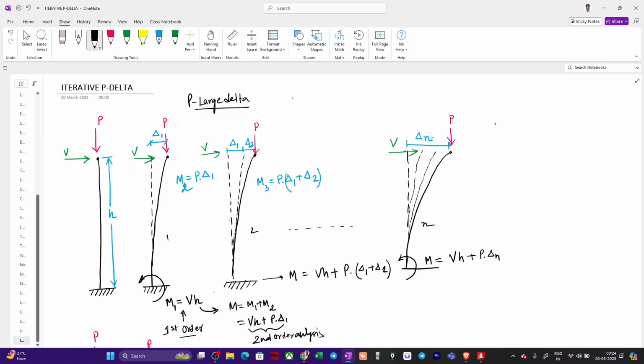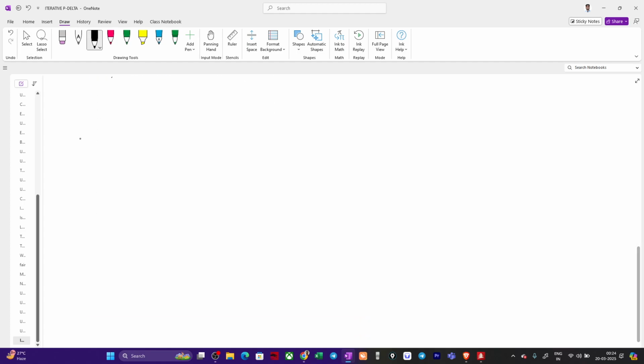But when we are creating a normal load combination by adding the values linearly, suppose we have got some force from the dead load, A, some force from the live load, B, and some other value, displacement or force, whatever it is, C. When we do a normal load combination, we linearly add those, so we are doing A plus B plus C, right?